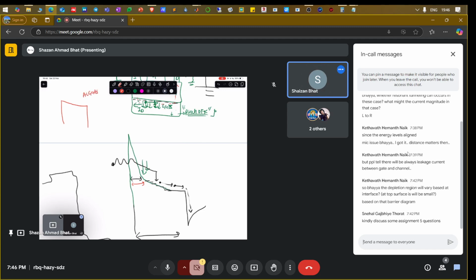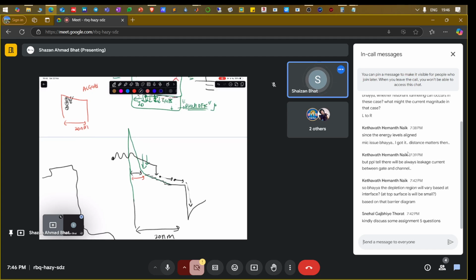Okay, this was 20. Fine. Up to this point, this is fine. Now you bring in some positive charge here, highly doped, huge doping. What does positive charge do? It will bring this band down, because now the electrostatic potential energy of the electron will lower at this point, because the electron will like to stay at this particular region.